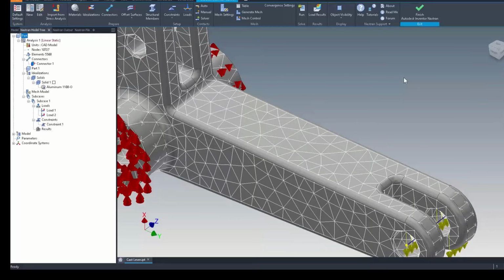that area. This typically will not happen on a natively created Inventor model. When you come from Inventor, go into NASTRAN dealing with those native surfaces, 99% of the time, everything is going to be pretty well intact. There's not going to be any kind of weird areas in the surface topology. However, if you've downloaded some components from Granger or McMaster-Carr, the way those exports were generated can severely affect their surface topology. You go and download a STEP file or an IGES file or an SAT file.